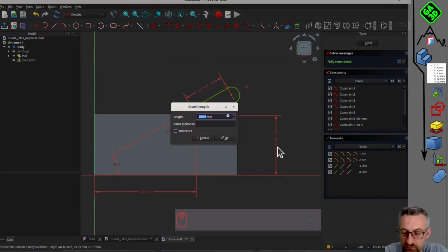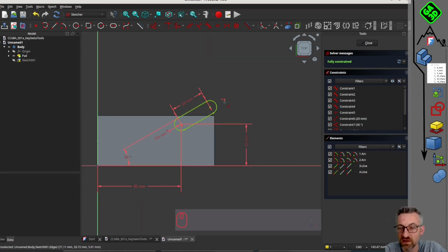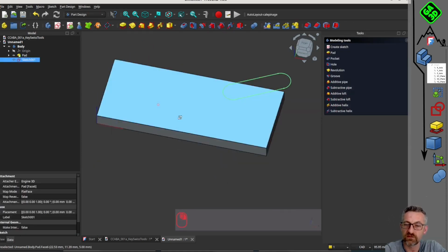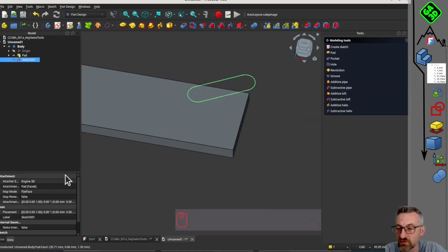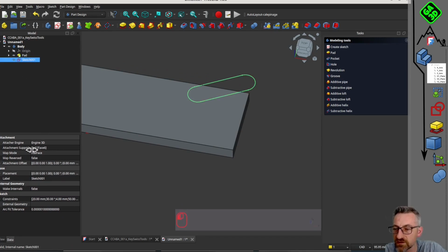If we take our sketch, we can only move it vertically. So we reselect our 2 points and define the height. Let's say 25, like this. There you go. Then we see that our sketch becomes all green. That means everything is well defined, everything is okay. And as long as you have degrees of freedom, there are elements remaining in white. We close that, we have another sketch placed here on the face.